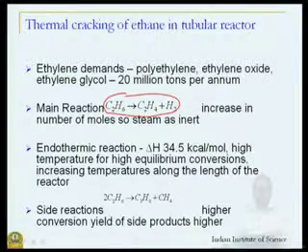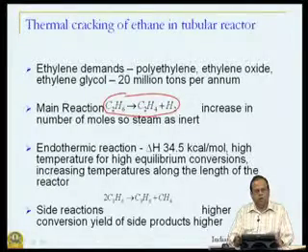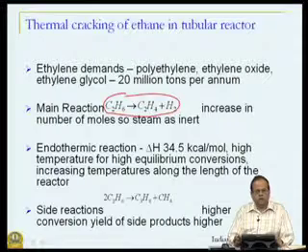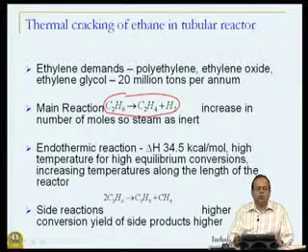So, it is an endothermic reaction, and the heat of reaction is plus 34.5 kilocalories per mole, a reasonably high value. Since it is an endothermic reaction, if you look at the equilibrium of this reaction, higher temperatures give higher equilibrium conversions. Now, we saw how to operate such reactors.